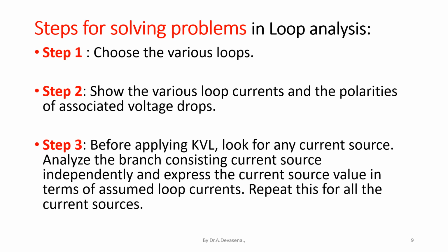Step 3. Before applying KVL, look for any current source. Analyze the branch consisting of the current source independently and express the current source value in terms of the assumed loop currents. Repeat this for all the current sources.